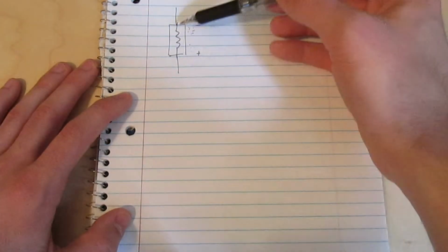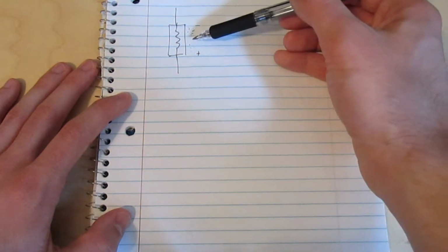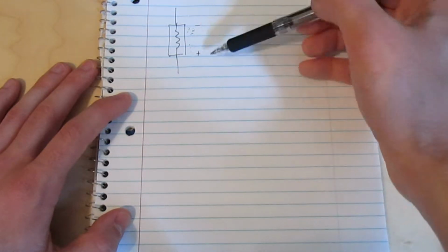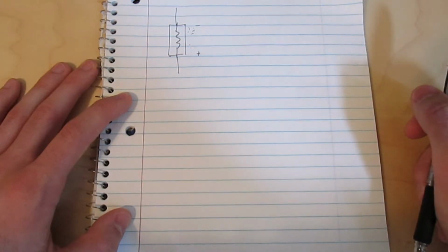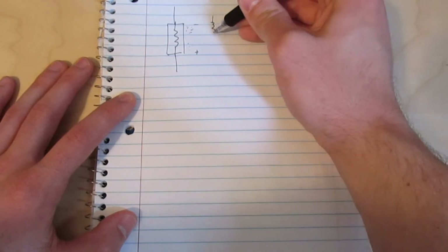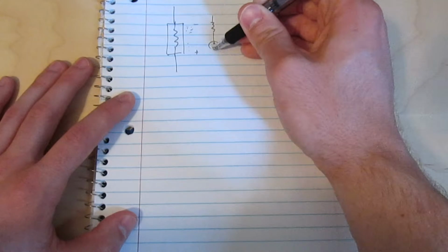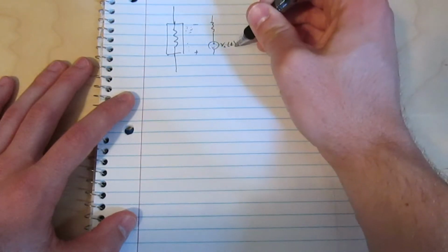Now these electrons are usually going to be spread pretty evenly throughout this resistor, so the average voltage is going to be 0 volts. But since they're bouncing around, there's going to be some random variation around 0 volts. And that's the thermal noise voltage of a resistor. And a useful way of modeling a noisy resistor is as a perfect noiseless resistor in series with a voltage noise source. We'll call it a Vn, which changes randomly over time.